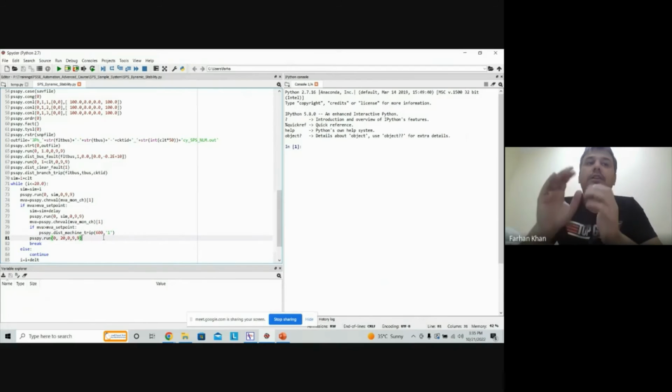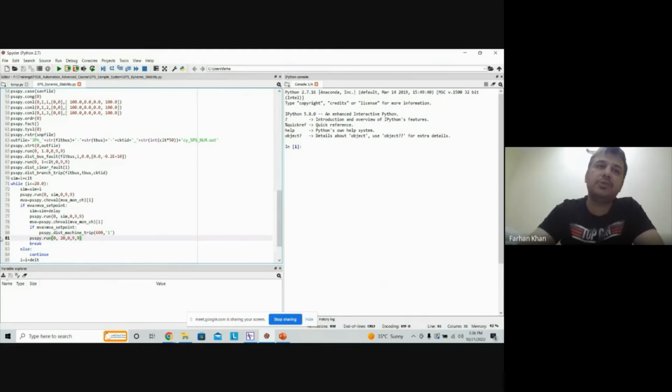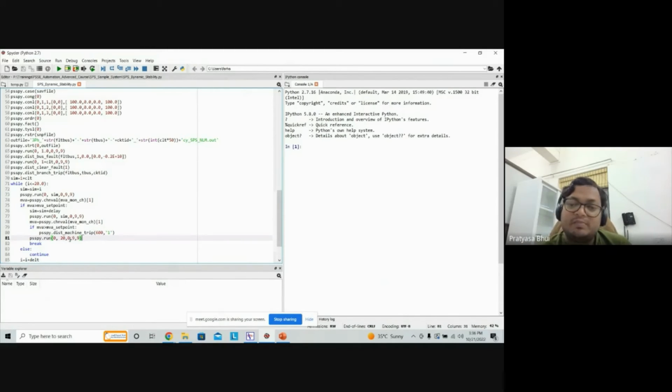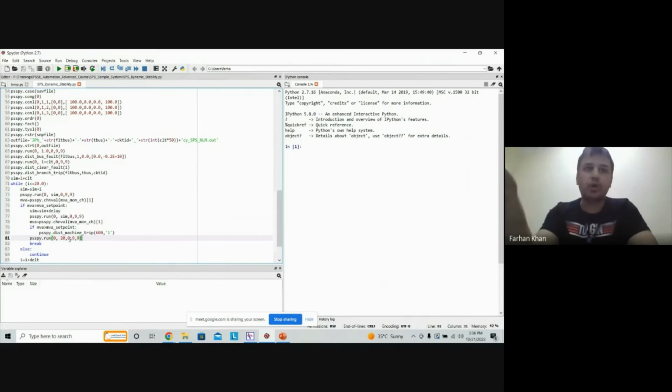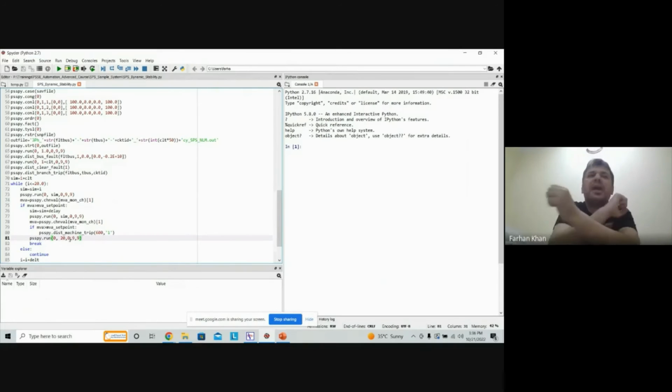And then run. Once you trip this generator, run the simulation for 20 seconds. So here you see 0, 20, 99. Is it possible to tweak any load? Yeah, of course. You can trip load, you can trip transmission line, you can do anything. If you want to switch your reactor, you can switch your reactor. If you want to switch your capacitor, you can do that. With this I should put it like this: sky is the limit. Whatever you do in your steady state, you can do this.